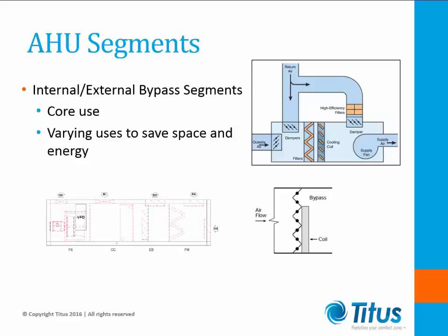When designing an underfloor unit, it is worth mentioning that all the humid outside air should be directed through the cooling coil and only return air used for bypass. This will help minimize space latent loads by preventing additional humidity from being introduced into the space from outside air through the bypass section. To address this concern, external bypasses work best.